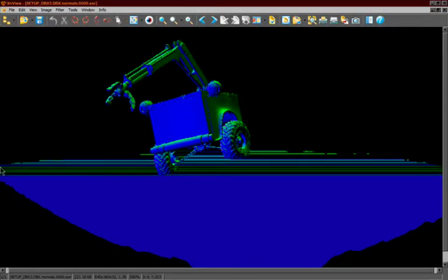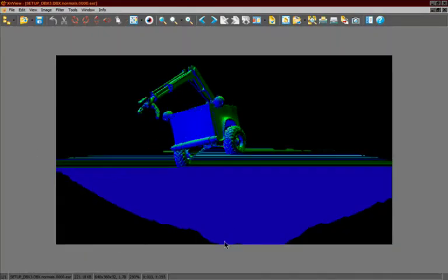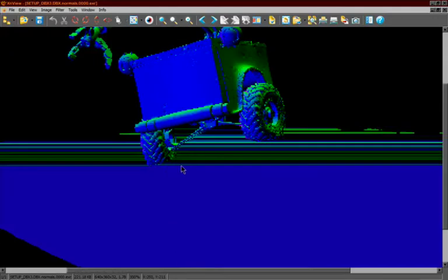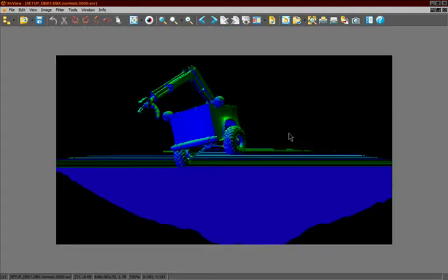As you can see, there's some artifacting going on, and this has something to do with the pixel filter and how it's artifacting on matte black objects, which the ground was. You just couldn't see it because it was a matte object, but this is the cause of it. You can actually matte this out using the alpha of a previous beauty pass, so it shouldn't be an issue.